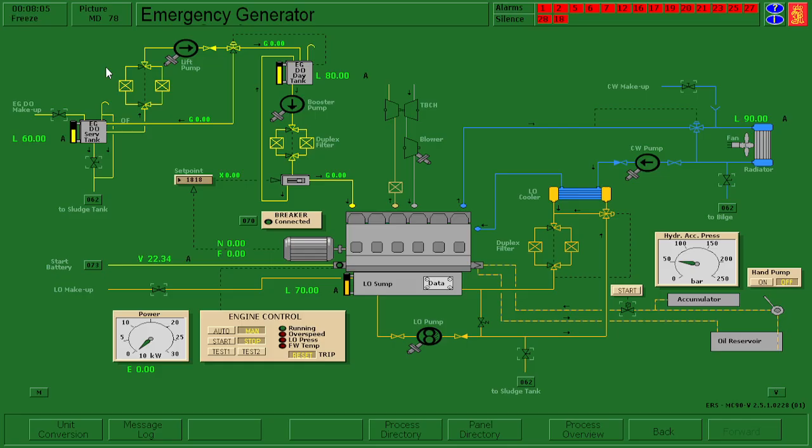So when you're using one filter, if that filter gets messy and it's ready to be changed, you just simply switch to the other filter. And in the case of food safety, you can very quickly clean off that filter. The clean filter has probably been sitting there for a while, you switch it over, and you're good to go. Then you can do the full filter change on the other side of the duplex filter. There is a bypass here on that system.